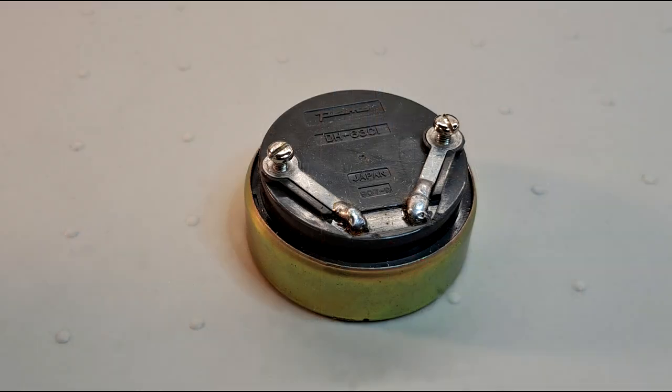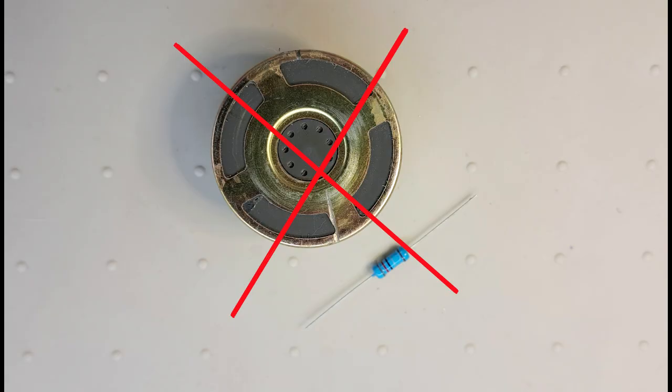The speaker in the phone's receiver is about 150 ohms and does not work the same way as the standard 8-ohm speaker included with the sound module. If you add an 8-ohm resistor to the original speaker, this will not resolve the problem. It may initially appear to be working, but if you attempt to use the original payphone speaker, it will not work reliably and the sound module will ultimately fail.